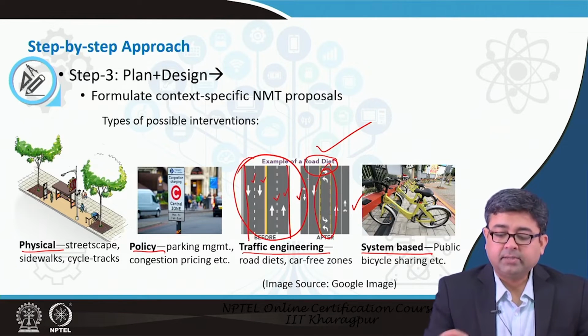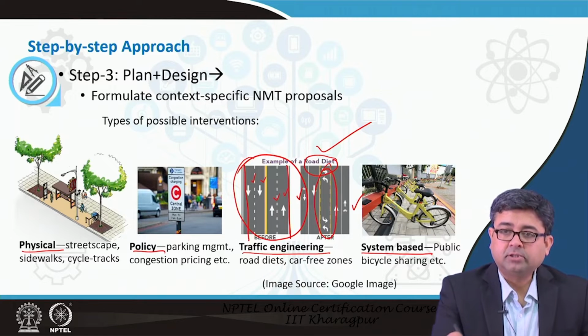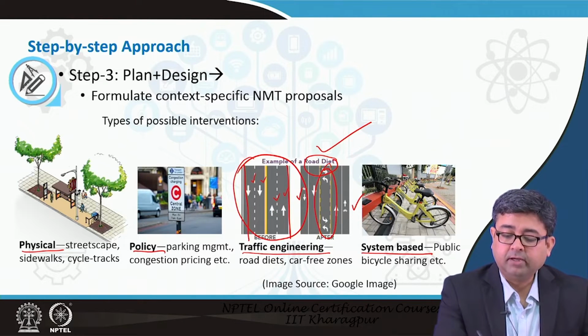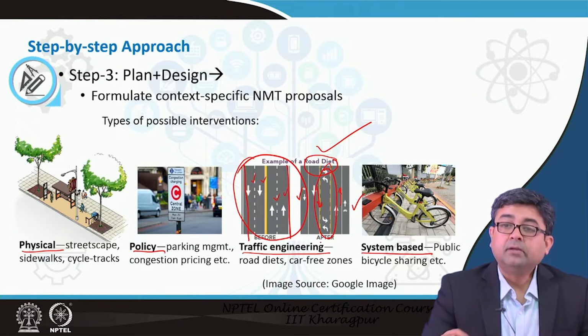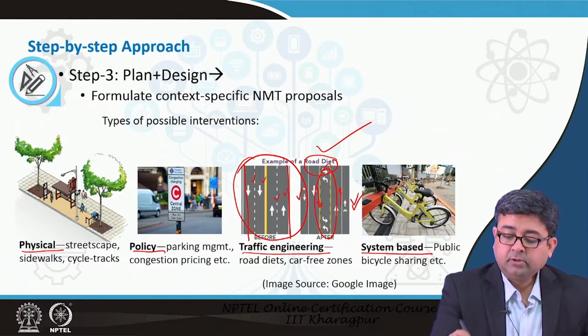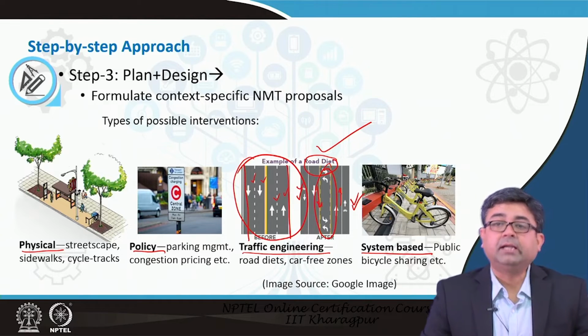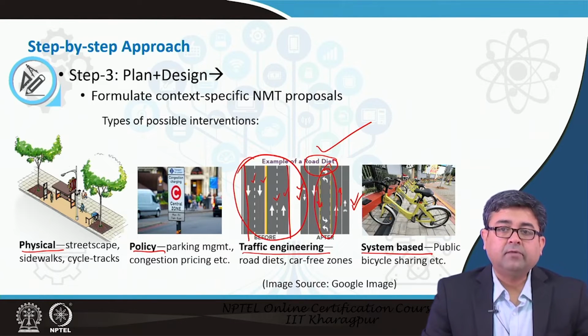So, the two-way lane is for anybody who wants to just cross the road; the traffic will only come there, otherwise that lane will not be used by motorized vehicles. So, now we have converted a 4-lane divided road into a 3-lane road: one traffic lane in the up direction, one traffic lane in the down direction, and one dual lane with 2 cycle lanes. So, now we have increased the potential of bicycles using this lane and made it a safe facility.